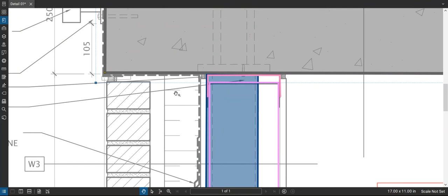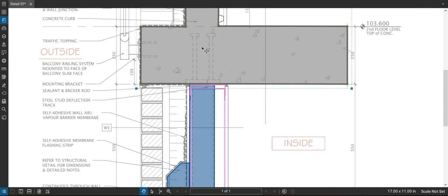There's less deflection to worry about obviously in concrete, but when you get into steel construction, based on the span the beams go in or something like that, deflection can easily get up to 3/4 inch, but your engineer can help you with what that deflection would be. But you always want to make allowance for deflection with the architectural elements. So that's what they've shown right there.